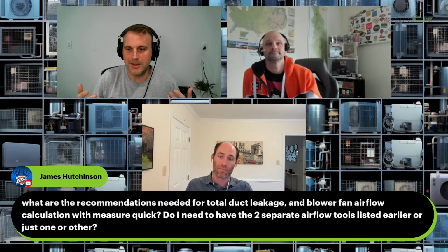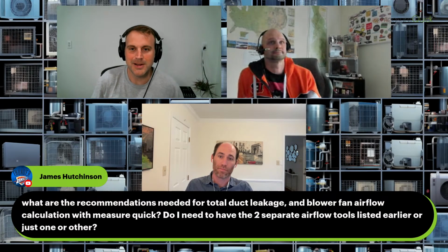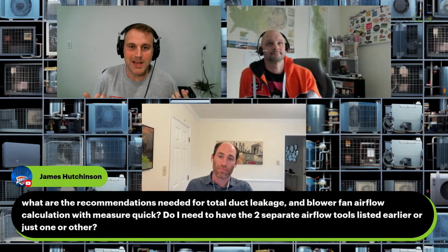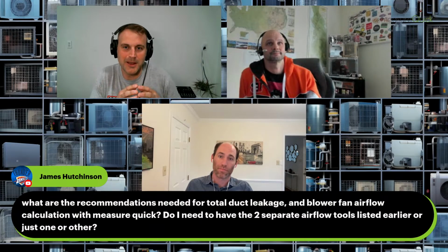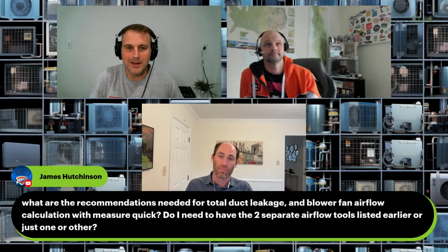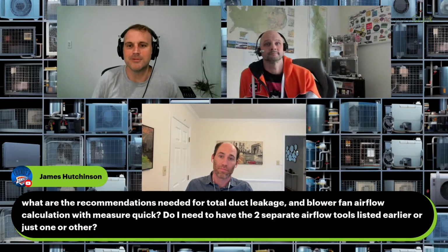But would I get a total external static pressure meter? Yeah. Now, this is where I'm going to be a little bit biased, and I would say maybe I'd get a DG8, because that's one tool that'll gateway you into the TrueFlow tool later. So if you can afford a little bit more money for a good manometer that you can use for all kinds of stuff, that's an awesome point of entry. Then you can use that to check external static pressure, and you have at least some barrier of entry to start taking that measurement, right? And then you could work your way up to a TrueFlow later.